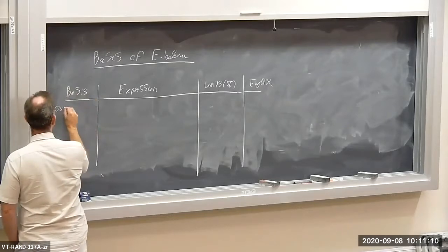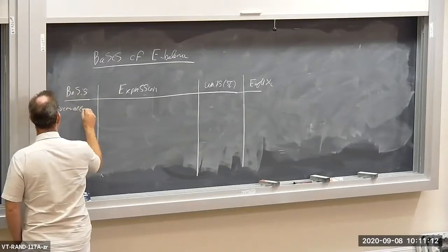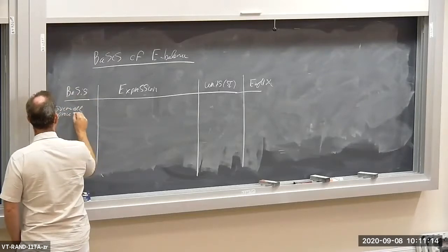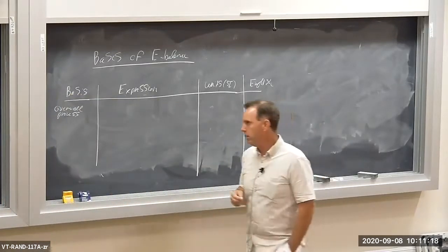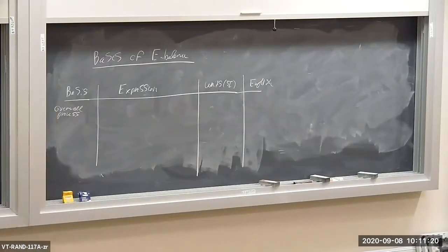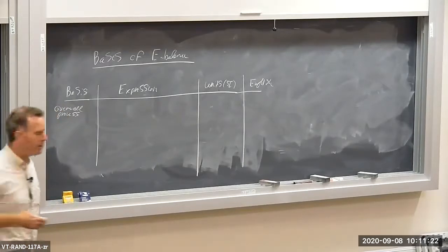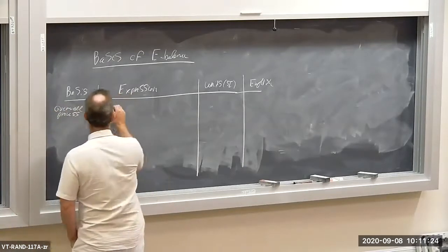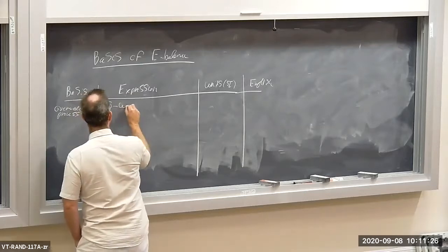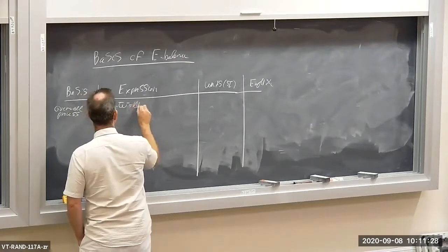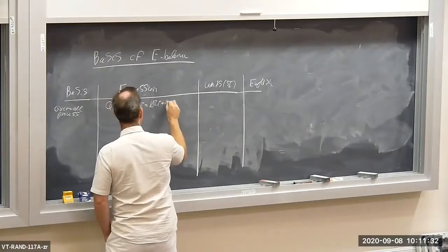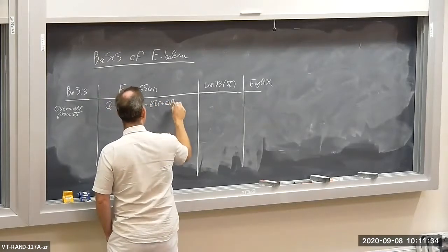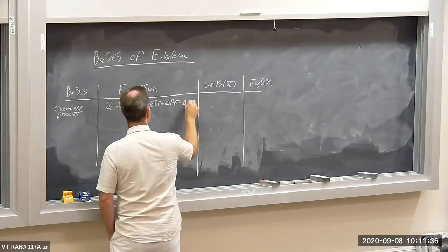So let's first write the overall process version of the energy balance. For an overall process, closed system, I'm just going to rewrite this equation right here. We have Q minus W is equal to delta E, which is equal to delta U plus delta PE plus delta KE.